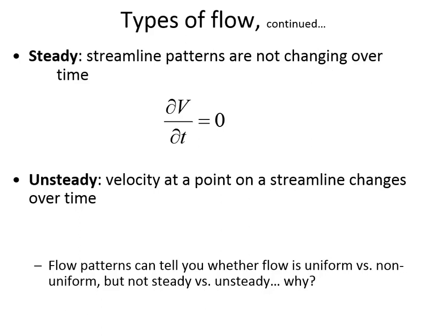So it was shallow water and then it got deeper, and this was what happened at 8 a.m. But then at 10 a.m. it was like that. So this would be both unsteady and non-uniform. So you can have combinations of each of these different types of flow. They're not exclusive. It's not like if the flow is steady, it can't be uniform or non-uniform. There can be any number of these combinations. So you can have steady, unsteady, uniform, and non-uniform.